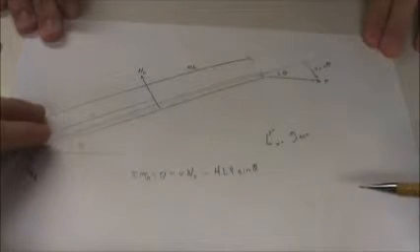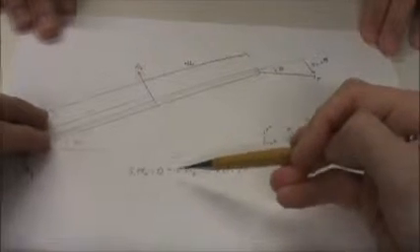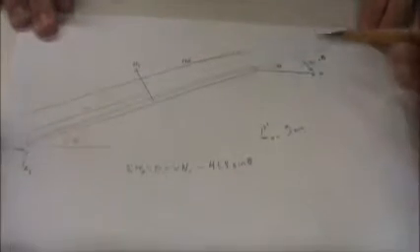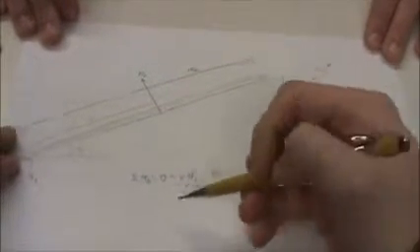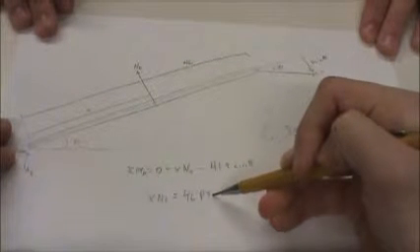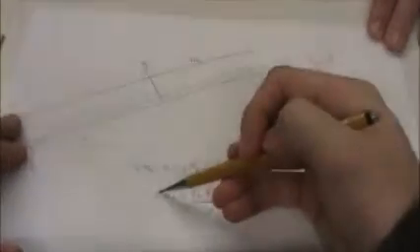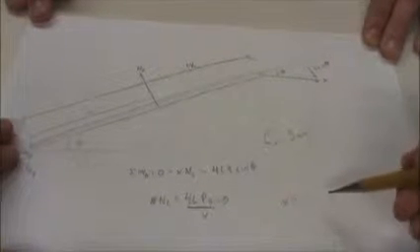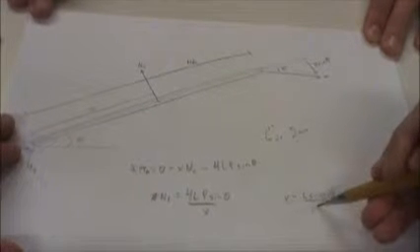What we're trying to do here is solve for the normal force C so that we can apply it to the other arm, CD, and find the moment M in terms of P. So this force here is going to be equal to this force up here. Let's solve for NC. x NC equals 4LP sine theta, so NC equals 4LP sine theta over x. And we can substitute in for x, which is L sine of phi over sine theta.